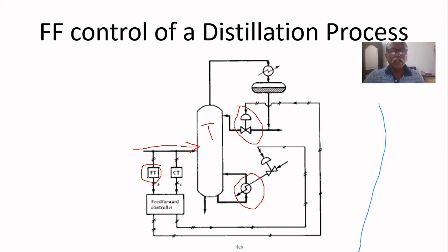That's why we can reduce the temperature here if we inject more reflux. The reflux ratio is particularly to improve the quality, and here it can reject this disturbance entering through this feed-forward controller. Anyhow, this disturbance definitely will reduce the quality of the product.